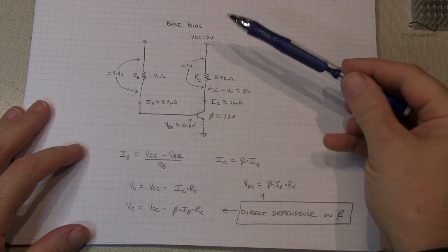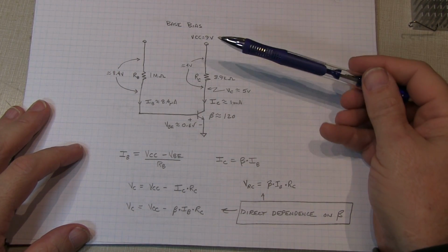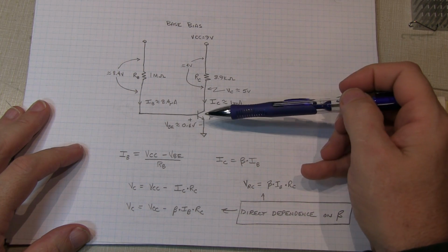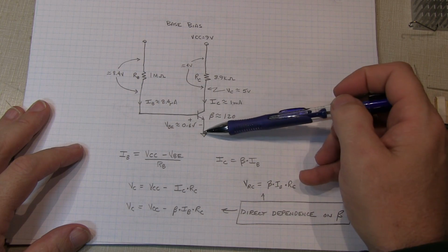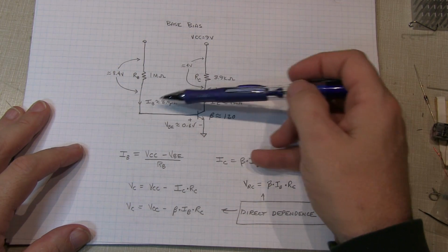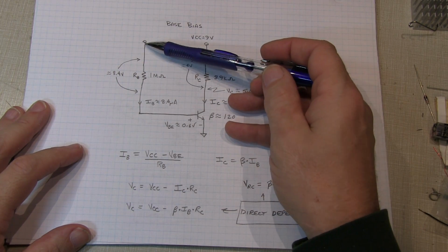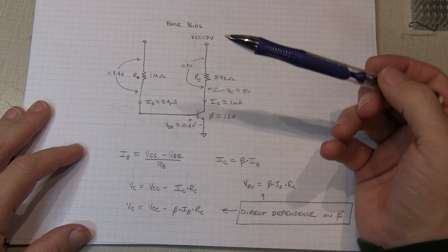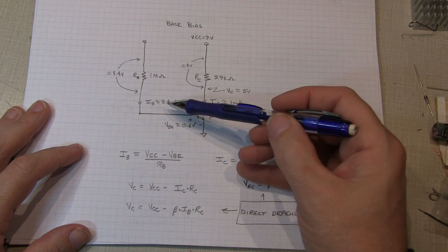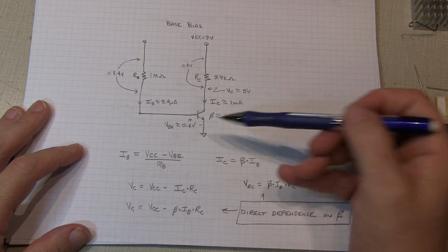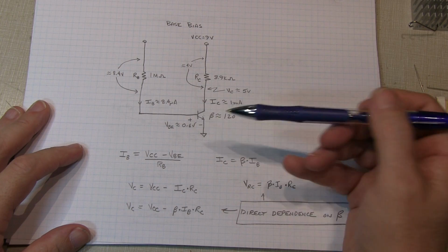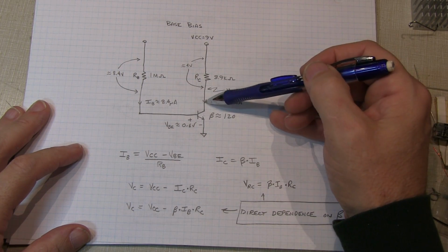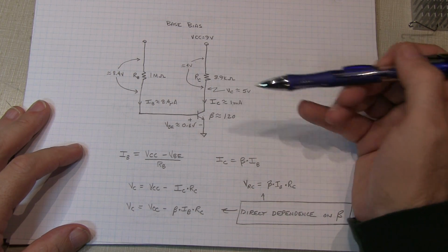In this first, fixed base bias case, it's actually quite simple. The base-emitter voltage is basically fixed. At these low bias values, it's about 0.6 volts. So the current in the base resistor is simply (VCC minus VBE) over that resistor value. That gives me the base current. And then the current flowing in the collector is simply the base current times beta, the beta value at that particular current level. And then obviously that current through this resistor creates that voltage drop.